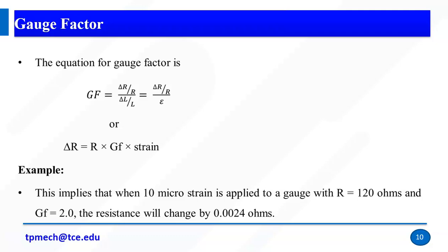So this is in mechanical deformation of a material. The mechanical deformation is converted to strain, but here the electrical resistance changes. So the electrical resistance change we will convert to the strain, right? Here delta L by L we know is the strain. So delta R by R equals strain times GF, and R is nothing but the resistance. So I can get the value.